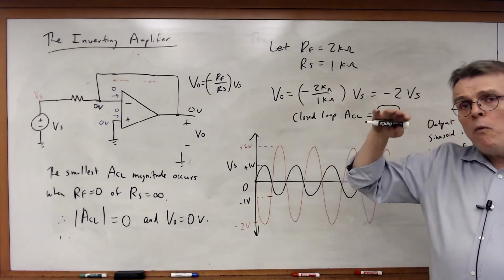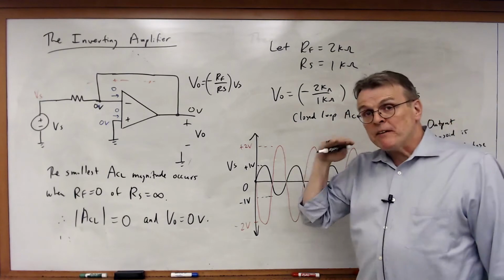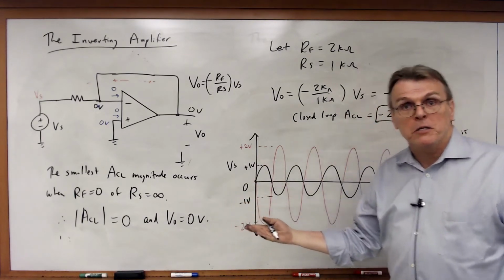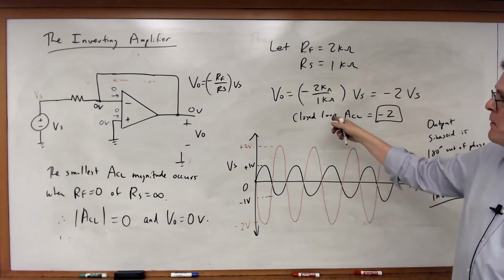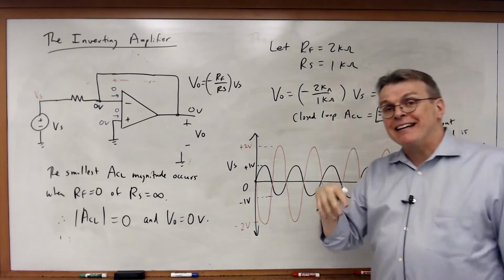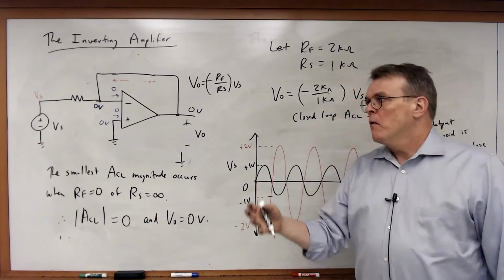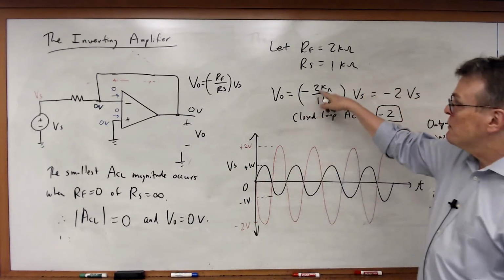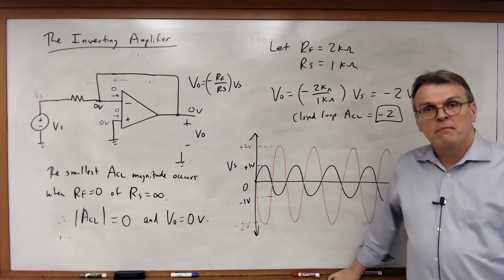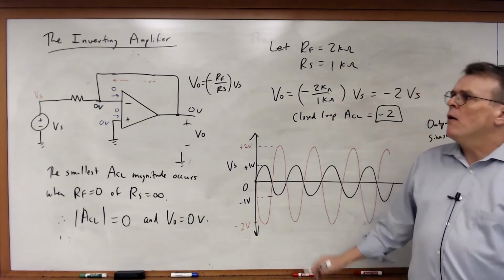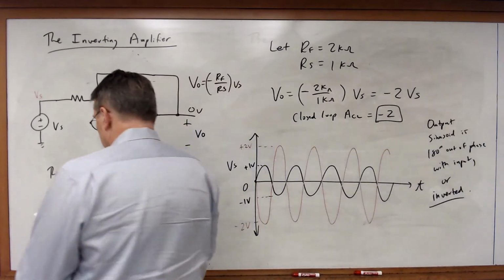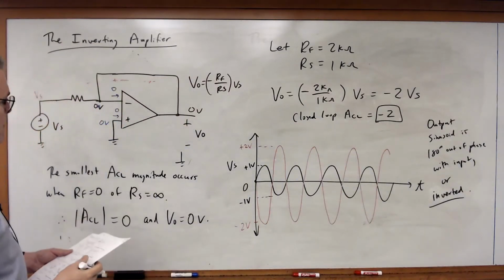So I can go all the way down to an amplification factor that's actually less than 1 or even equal to 0. So really I could build this thing to be not just an amplifier, I could make it into an attenuator where the output would have a smaller magnitude than the input if I chose the correct resistor ratios.